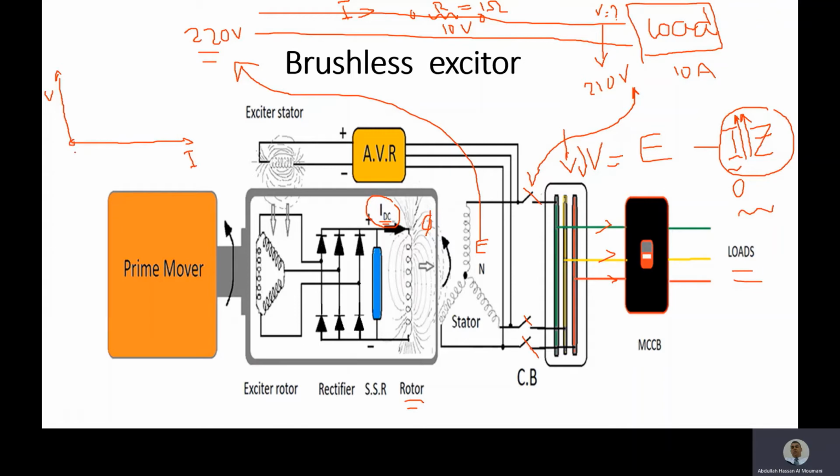At zero current, or with no load, the voltage will be equal to the required voltage, say it is 440. When the current is increased, or when you operate more load, the voltage will be reduced like this, until at a certain point it will reach what? It will reach zero. The output voltage of the generator will reach zero.